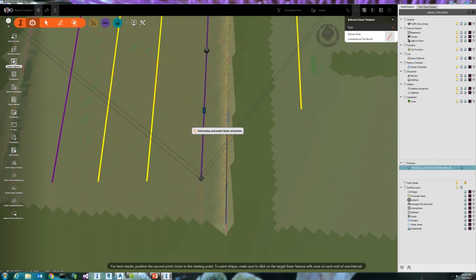Usually the top and bottom are purely elevation based, and it obviously needs to be accurate for the design work. So the software does a really rigorous job making sure it picks up proper points. As many of you might have dabbled with the point cloud already, point cloud doesn't get the exact point you want, not all the time, some of the time or most of the time depending upon your collection. So in those cases the software makes a best judgment. That's where the cross-section comes into the picture, to help you correct those things.